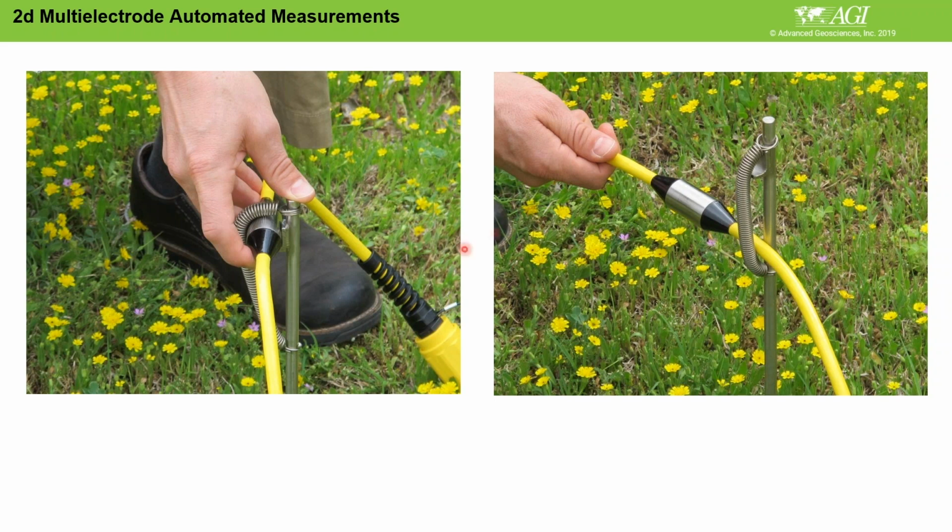But our recommendation is to use this very tightly closed spring that pushes your electrode and keeps your contact resistance safe throughout your measurement. Because in the field, when you do automated measurement, you're not doing a 5-minute measurement. Maybe you're doing half an hour, 1 hour, 2 hours. This makes sure the contact resistance is really good during those measurements.